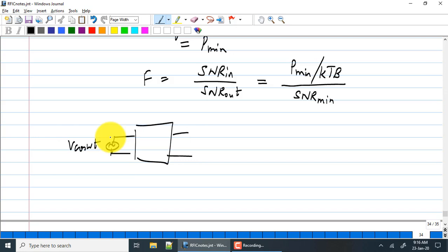Since you have designed your circuit to be as linear as possible, the output is only going to be a linear combination of the inputs as far as the signal is concerned. Which means you would find the gain for every Fourier component and find the output. The gain does not change.